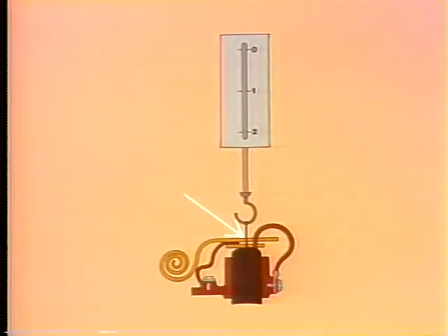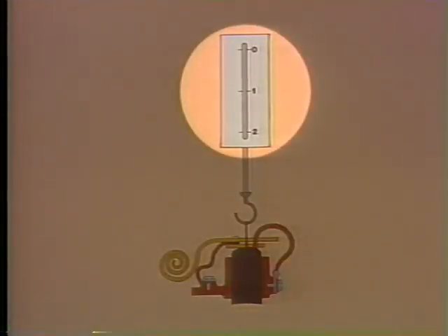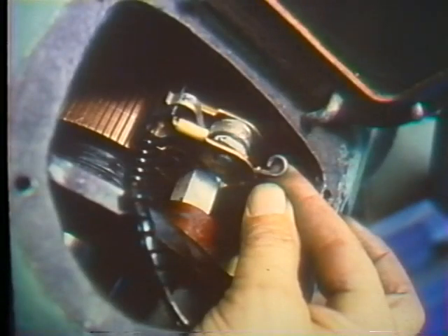If the manual has disappeared, well, you could figure it out mathematically. After you've found out what it ought to be, you can use a brush tensioning scale. Attach the scale to the tensioning arm and pull until the brush just clears the commutator. Then read the scale. Adjust the tensioning device until you have the correct pressure. Now connect the brush pigtail to the brush rigging and make sure the connection's tight.